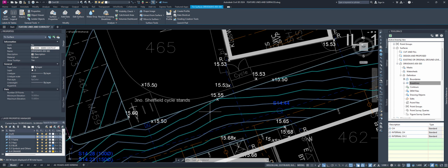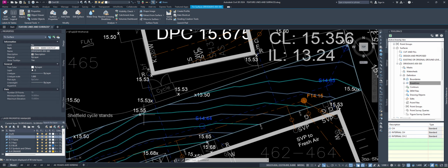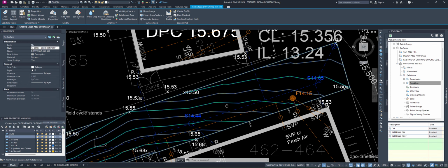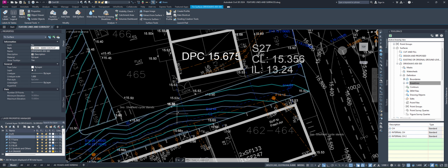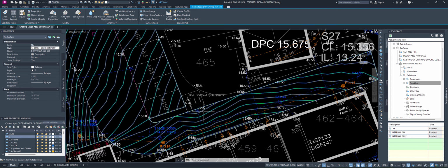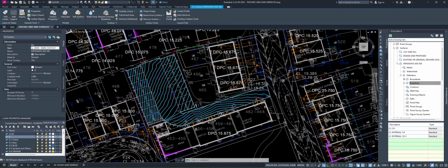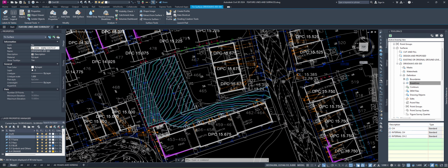To be honest, I'm not really amazed with that little bit in here, but again, it shows it's going to work. So we're creating a high point here, pushing this way and that way towards this gully, and then from here we're creating another high point pushing back towards this gully and down this way. So as you can see, the drainage is going to work better with the little changes we apply.